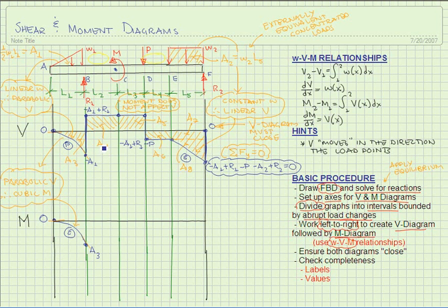Continuing along with the similar logic, we know that our moment will now change the magnitude of this area, and that is a positive area. So we will have a positive change. Since we have a constant shear, we have a linear moment curve. Since that is constant, this is linear. And we'll denote that with an S with a circle around it. And we know that this magnitude is a negative value for A3 plus A4. And I'm just going to call that the moment at point C.